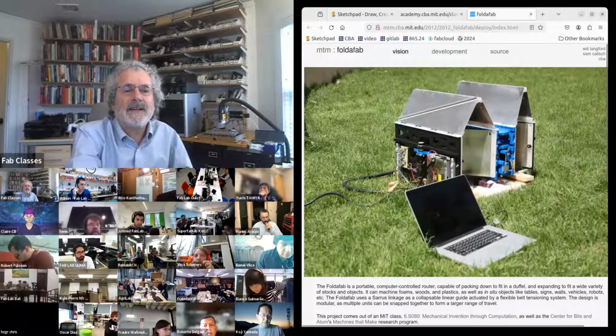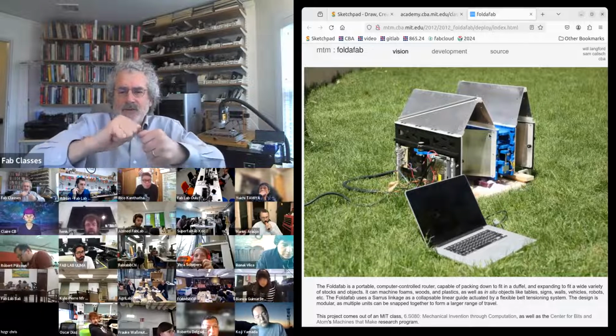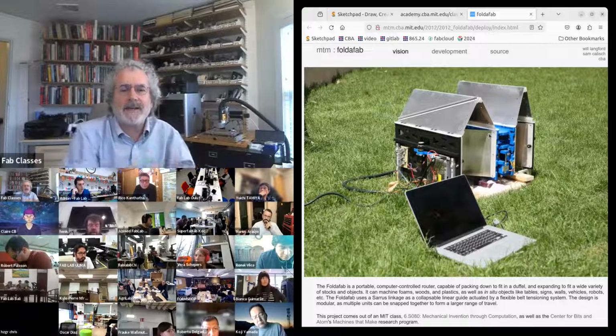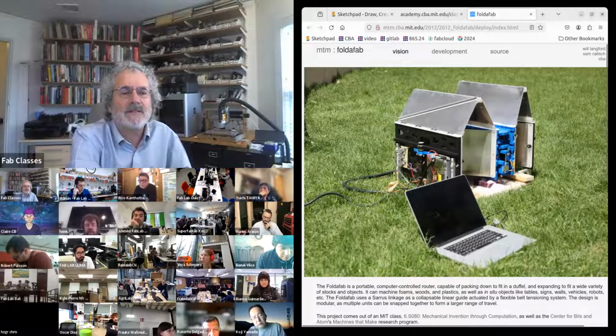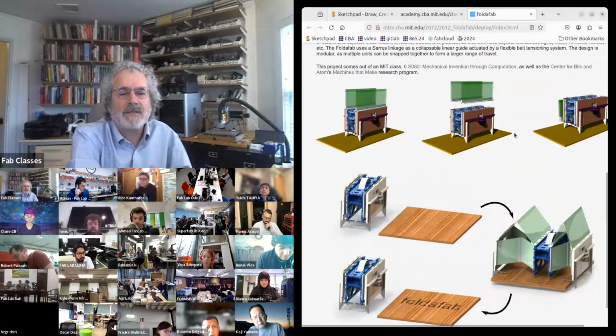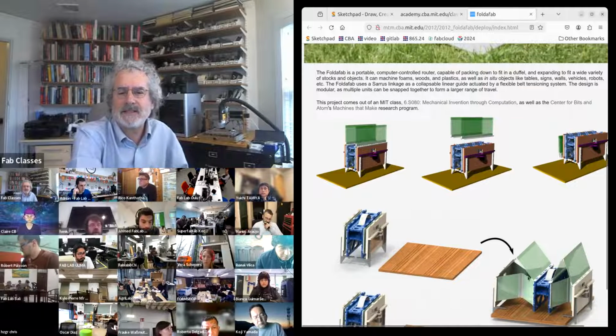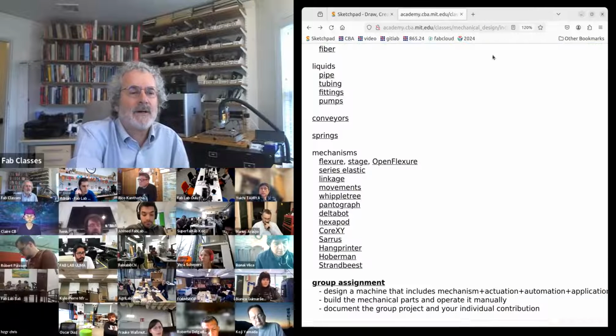Saurus is an interesting idea. If you machine a thin hinge, if you twist it, you'll tear it. But if you don't twist it, you can bend it, and it makes a flap. And so this is actually a motion system that's just based on flaps. And so 3 flaps makes a linear axis. And then this turns all of that into a motion system.